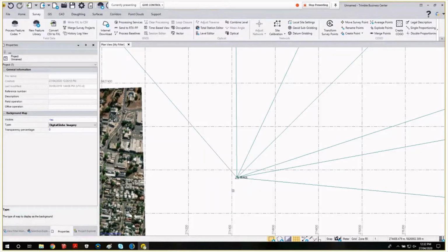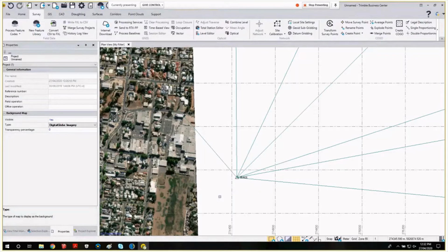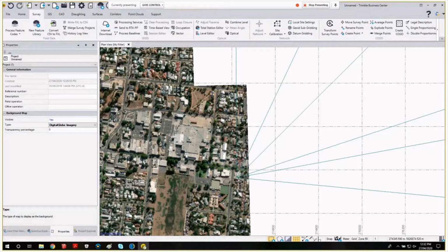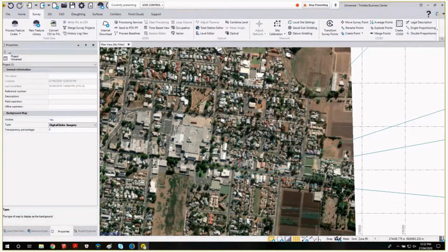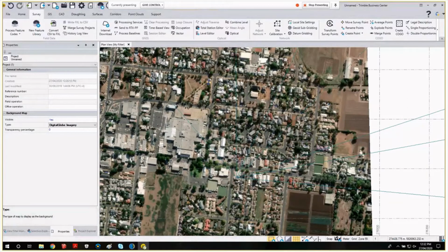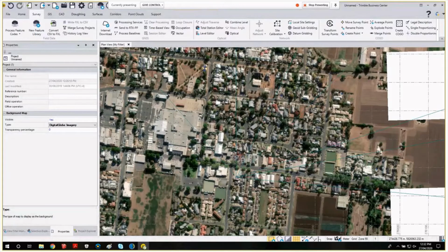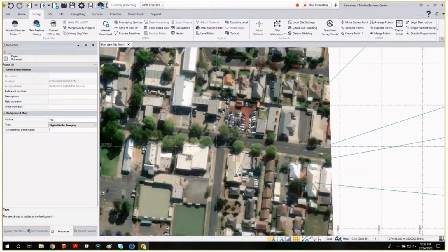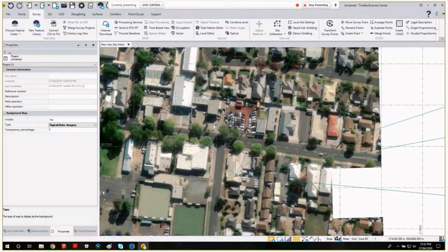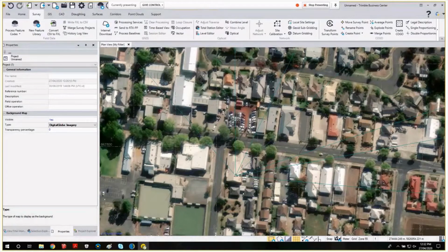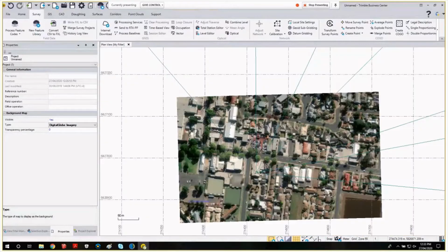You might find that it's in a highly obstructed position, and that the results coming out line up with the position the receiver was in. Once this caches, we'll see that this one, like most of the CORS sites, is set up on top of roofs to get out and away from any local effect and multipath, to give the best possible satellite tracking. It's quite handy to be able to jump in here and see its real world position without going out to Google Maps or anything else. Okay, I'll switch those off for a second.